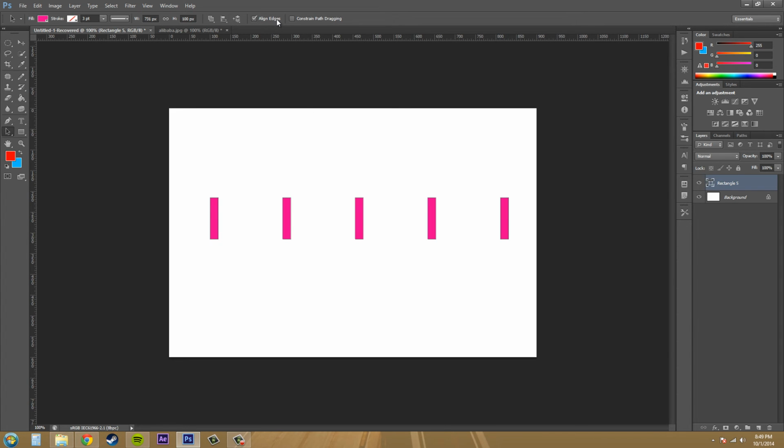When you have that on, pretty much what it does is it aligns all the shape layers to an internal pixel grid within Photoshop, and that ensures sharp outlines. So you basically just want to have that on all the time. When you're working as a web designer or working on other web things, you can see that this will help out a lot. And if you take it off and try to put things into your design, they're not going to look as nice and sharp on the edges. It's going to look bad. So make sure you basically always have that on.